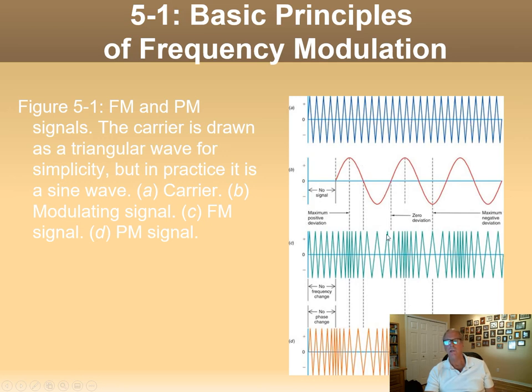And here's the modulation, and when you apply that modulation to the carrier, you get these changing frequencies. See, this is modulating to a lower frequency, and it modulates up to a higher frequency. One thing that's important to note here is that your 2206 device in the lab has an inverse transfer function, meaning that when the amplitude comes down, you're going to get a higher frequency. When it goes up, you're going to get a slower frequency. It doesn't matter. It's going to sound the same in your speaker if you're using it as an FM receiver. It's just that the phase is the opposite.